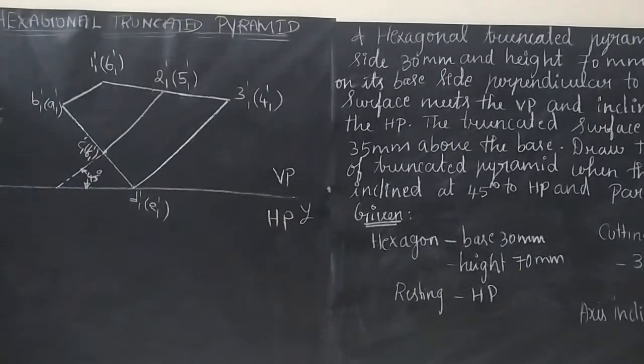So whatever we see in third unit is just a replication of it. Just recall it. If you want to tilt the axis, it's more than enough if you tilt the base itself. See here, if the axis is 45 degree, and this angle is 90, the remaining angle will be 45 degree obviously. So just measure this distance between B dash, A dash and D dash, E dash. For example, if it's 5 centimeter, keep your protractor anywhere on your reference line.